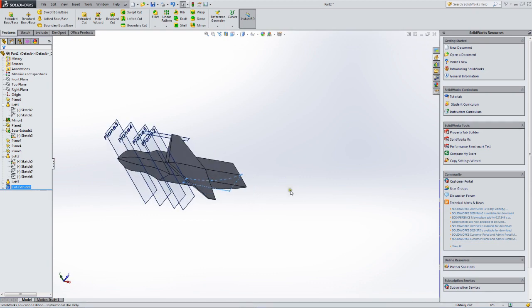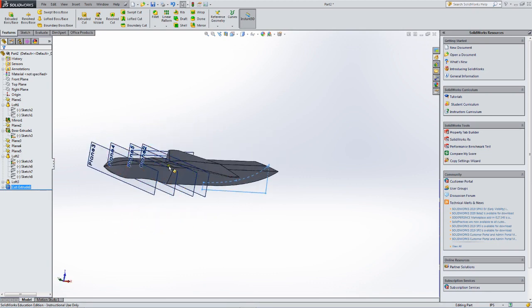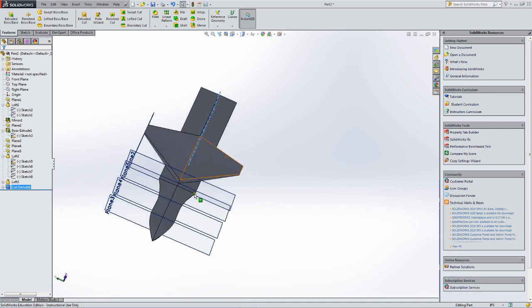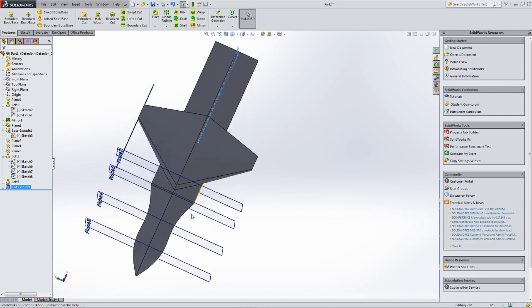The only thing I have to do now is add, I could add strakes up here. I could add butterfly tails. What I am going to do is add the strakes. The thing about stealthy airplanes with twin inlets, and all stealthy airplanes I'm aware of have twin inlets, nobody's trying to be stealthy with a single inlet on the underside. So the thing about twin inlets is that they have to be chined. That means they have to have a sharp edge on their outer edge in order to minimize their radar cross-section